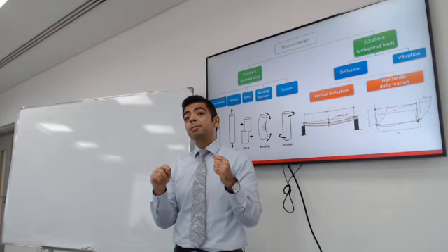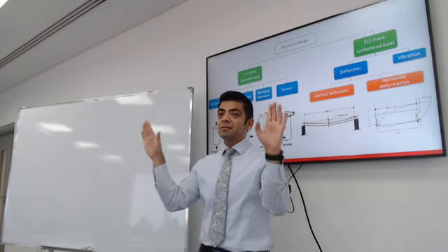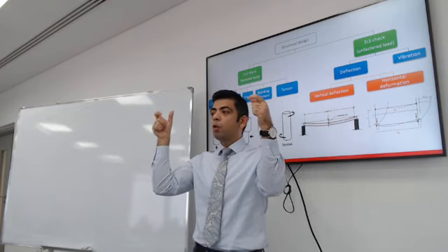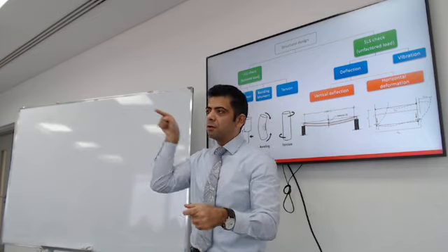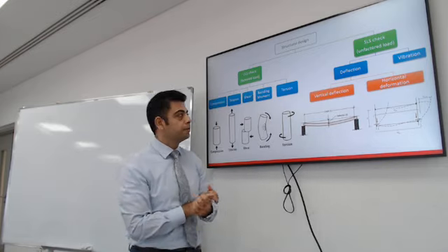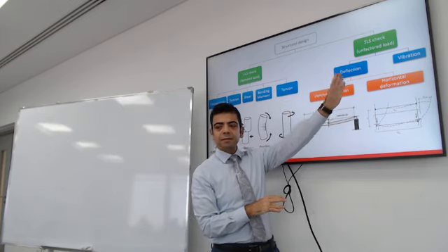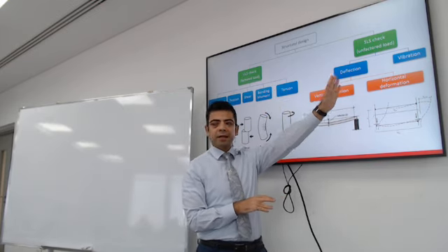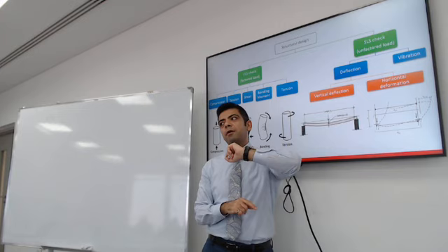Also in industrial buildings that have cranes. I'm going to show you how that works. When the crane stops, it puts a horizontal force on the structure. These are the service limit state checks, and we check them with unfactored load. That's very important.